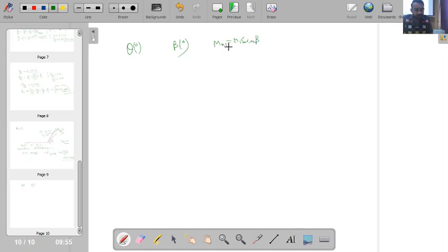Then corresponding to this Mn1 I can calculate the value of Mn2. Fine. And then this Mn2 I can utilize to calculate the value of M2, which will be Mn2 divided by sine of beta minus theta, and here I will use the normal shock relation to calculate Mn2.